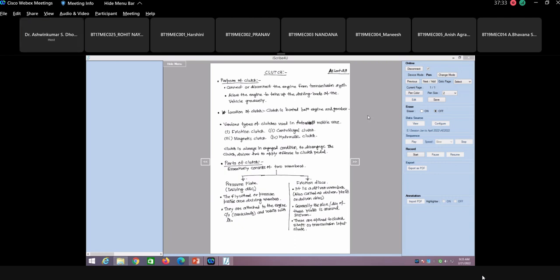तो सर आपको ये समझना है कि क्रैंकशाफ्ट को जो लगे हुए प्लेट्स है, they are pressure plates, sometimes they are called as the driving disc. So if you use driving disc, that is the good thing, because then we are very clear कि driving disc अगर बोल दिया, so these are directly connected to the crankshaft, and the other one is the driven disc. These are connected to the input shaft of the gearbox or the transmission system.